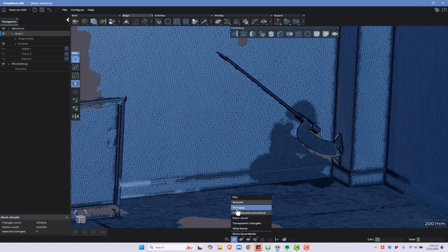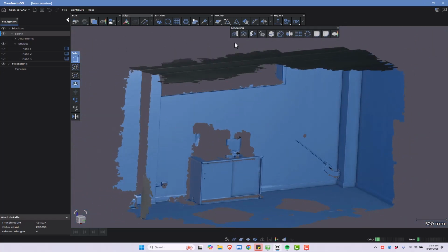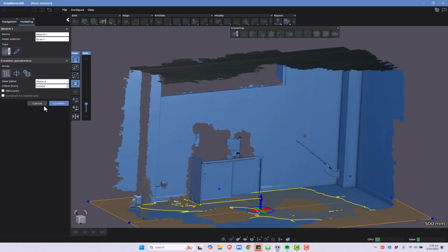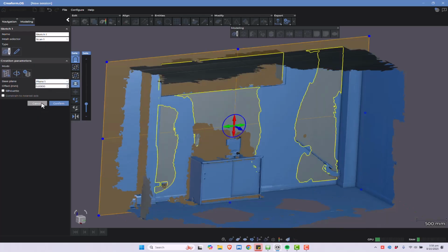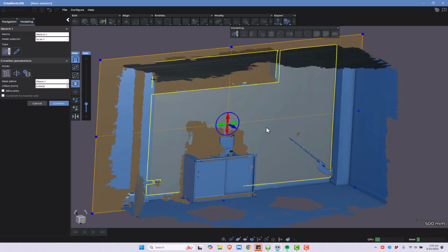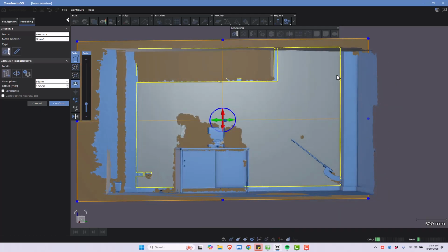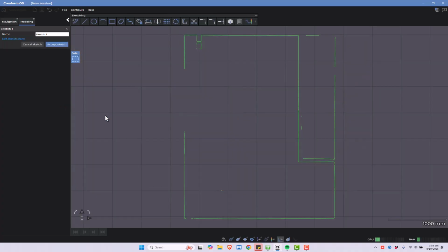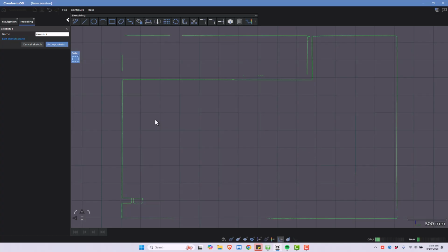So now what we're going to do is create a sketch over top of our scan. So with the Scan-to-CAD Pro, again, which comes with the HandySCAN MAX, we can choose our start plane, and that was plane 2, no, plane 1. We could then bring out this cross section, maybe 5 millimeters, and we're just after all the areas of interest around the window, around these PowerPoints, and then we can confirm. And that creates a polyline that we can snap to.